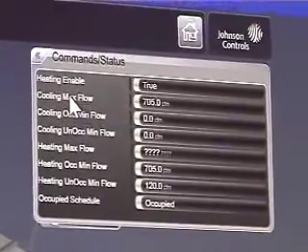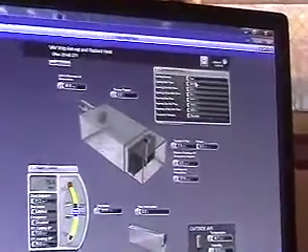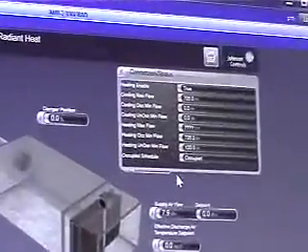If we don't have heating available, like you've disabled the heat exchanger or whatnot, we have it set up so that if we don't have hot water, we actually disable the heating enable. That way, if the box is trying to heat, it doesn't blow more air into the space trying to heat something, even though it's actually cooling the space. So that's something to watch for. You shouldn't have to do anything with it. It should automatically take care of itself. If you're looking at it and say, why isn't it heating? You might want to make sure that your heating enable is set to true.